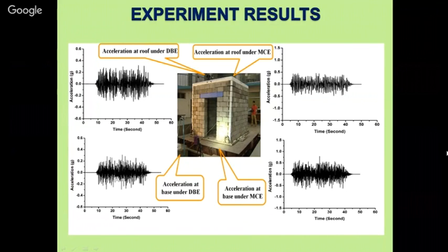Here the weight of one stretcher block we have kept around 20 to 21 kg, which is nearly equal to 6 bricks joined by volume. So that lump of bricks will weigh similar to 20 to 21 kg, or maybe 19, so the weight of the concrete block and the 6 bricks is nearly approximately the same.